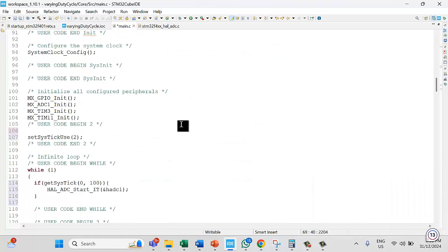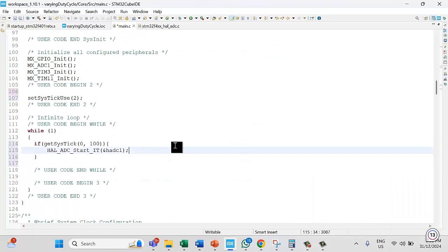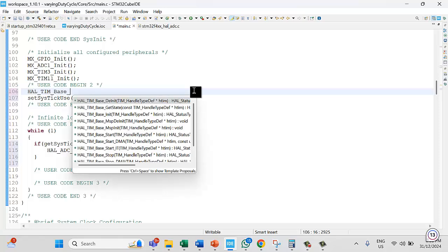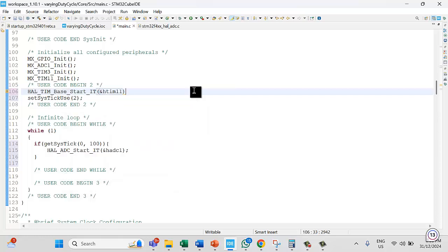Now we go to the second one, for our display. We start the display first. So in the display, we need HAL_TIM_Base_Start_IT for TIM11, right? We're not using the UG part or the timer interrupt flag for the TIM3, so we use TIM11 only for this case.